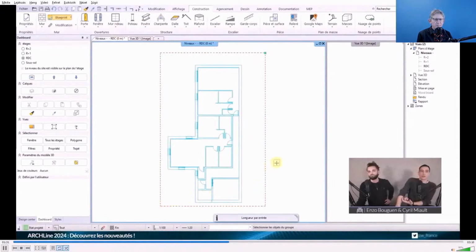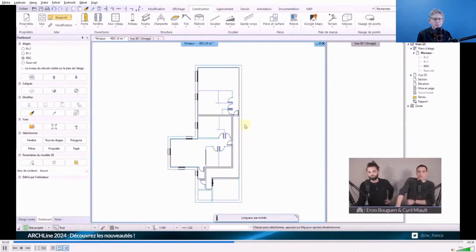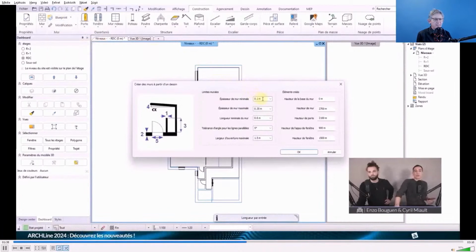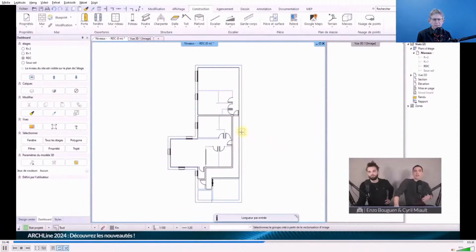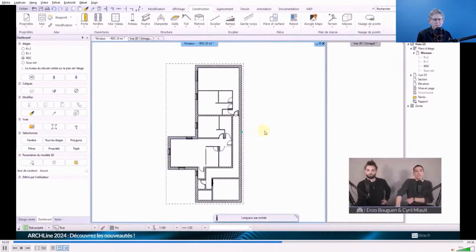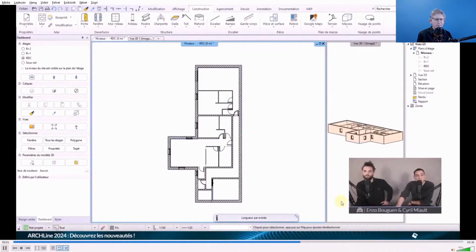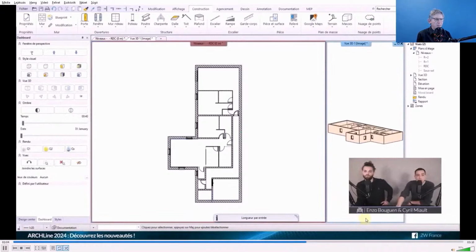A well-organized DWG floor plan uses many layers, which are also displayed in ARCHLine XP. The accuracy of the conversion is significantly improved if the filters containing these elements are turned off before the conversion. Overall, depending on the complexity of the design, several hours of work can be saved with the new algorithm of ARCHLine XP 2024. Architectural models of several hundred square meters buildings can be completed in a few minutes.